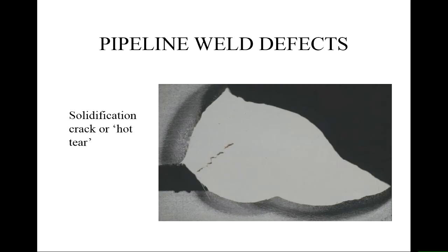What else have we got here? Solidification cracking or hot cracking. In many cases it might be difficult to make the distinction between what is caused by hydrogen and what is caused by solidification. Why solidification? During heating, usually all materials expand. During cooling, all materials contract.